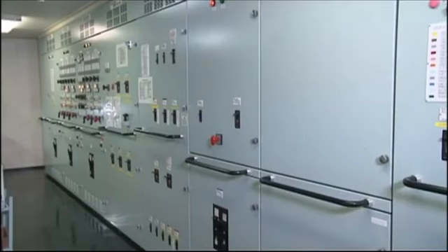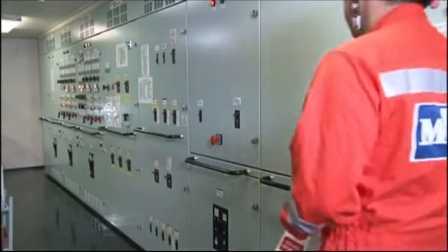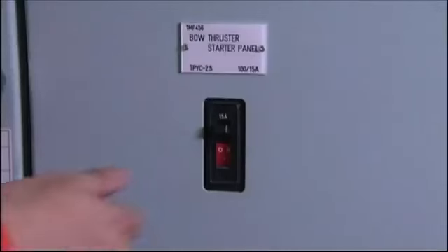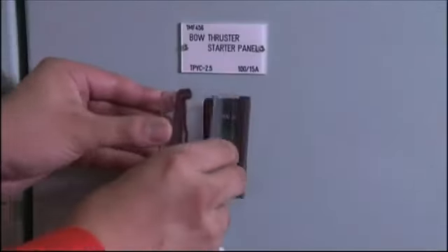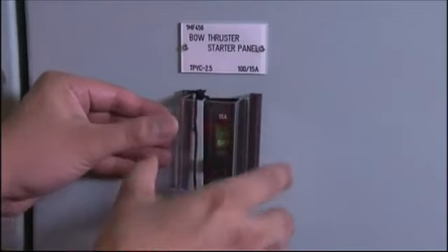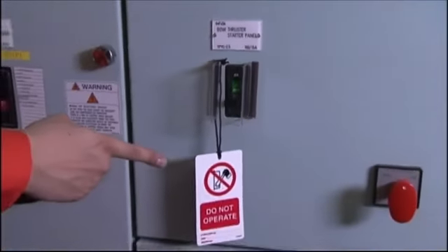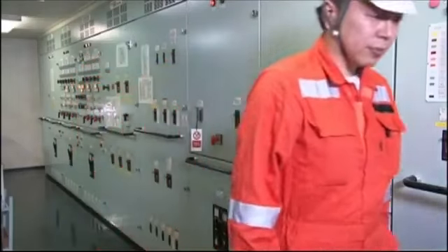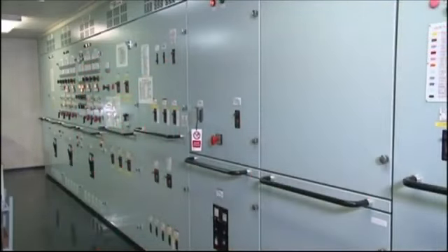When engaging in operations that require power to be shut down, post "under maintenance" and keep "power off" signs so that power is not mistakenly switched on. Always remember that accidents involving electric shock are prone to occur immediately before work is completed. Never ever let down your guard until you leave the danger area, even if your work is finished.